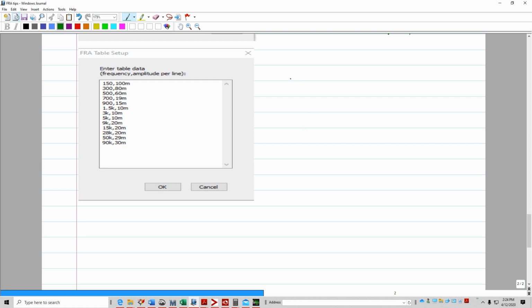Okay, and in power supplies, typically, since your gain looks like this, at low frequencies your signal has to be a little bit higher, and then at the crossover frequency, you want your signal to be a little bit lower, and then as you go into the high frequencies, you want to increase your voltage.